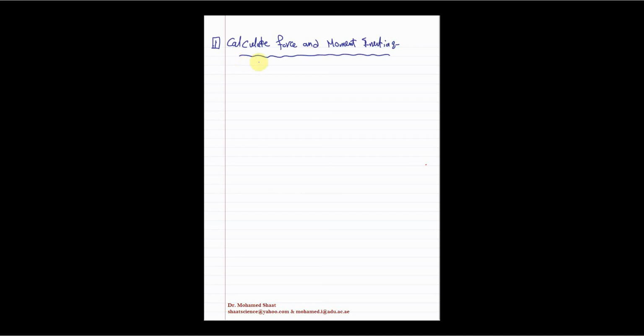So we said that generally the magnitude of the inertia force should equal the mass times the magnitude of the acceleration of the mass center, and the inertia torque should equal IG, the mass moment of inertia of the link, times the magnitude of its alpha, or its angular acceleration. Make sense? So we're going to use these two expressions, and we're going to do the calculation for link 2, link 3, and link 4.